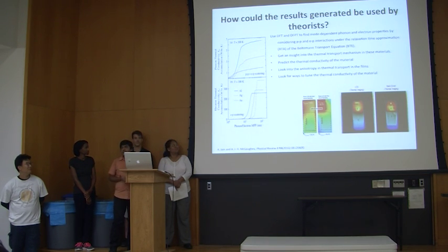And also we know that there can be certain ways of tuning the thermal conductivity of the material, that is, increasing it. So suppose if you strain the system, the bonds get stiffened and the speed of sound increases, and it's expected that the thermal conductivity increases.